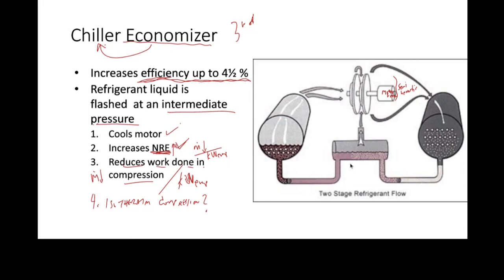And what we're going to see is that this economizer is also going to have an intercooling effect, because that's what we did with air compressors, right? Now, the only way we can intercool is we need to have multi-stages. Okay, you can't intercool a single stage machine. If we're going to intercool, we need to have 2 steps of compression, and in between we are going to do some intercooling.